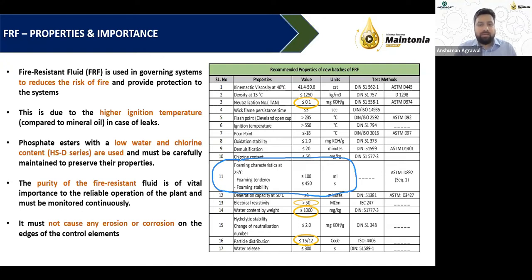High to an extent that the foaming height was approximately 1 foot, which I understand is very high as a practical professional for these systems. Because of foaming, the related problems in your pumps, in your entire system, the noisy operation, hunting, all of these are related to foaming in the oil.